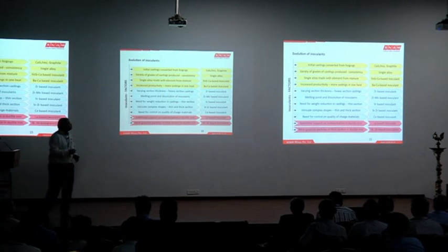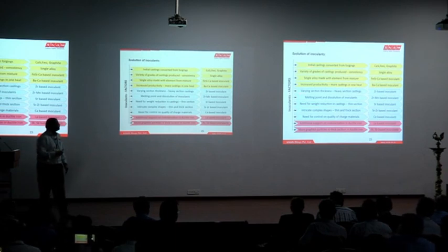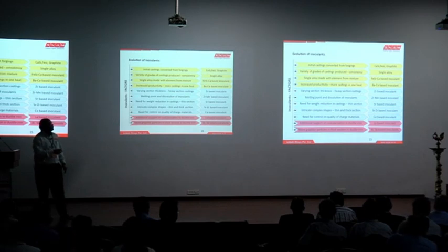ductile iron material. When initial castings got changed from forgings, the initial set of inoculant would have been sufficient. When different grades of castings were required, a single alloy, maybe a composite of everything, would have been sufficient. And a single alloy made with different elements in a mixture, say for example manganese, copper, and varying section thickness come up, a new inoculating type would have come.